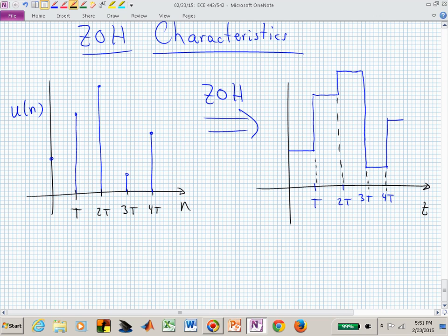Is it clear what we're doing? You're just going to obtain a sequence of numbers. You'll be handed a number, and you want to then hold that numerical value and create that signal that's then supplying your analog system, whatever is on the output of that zero-order hold.